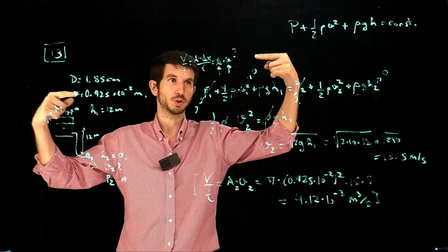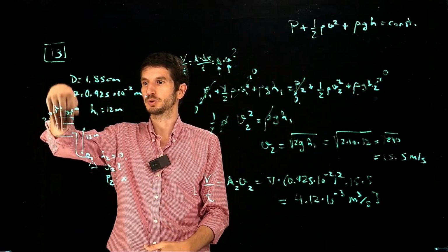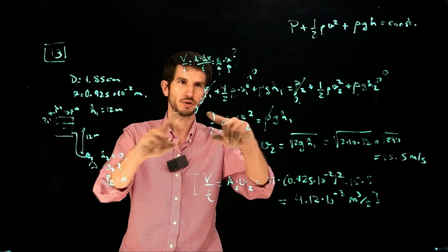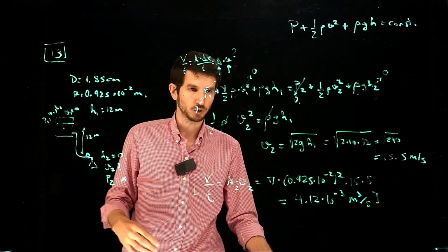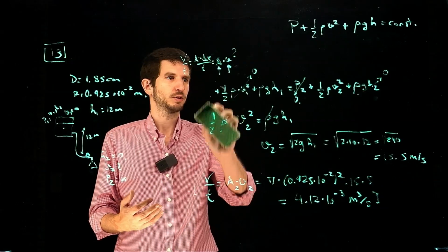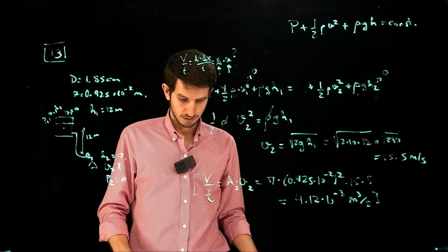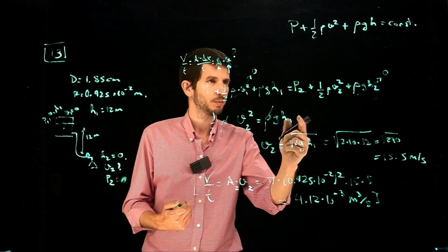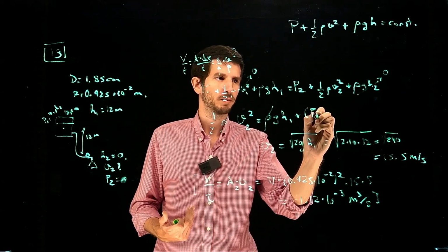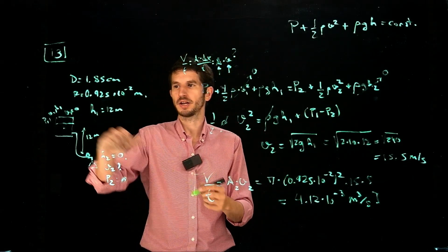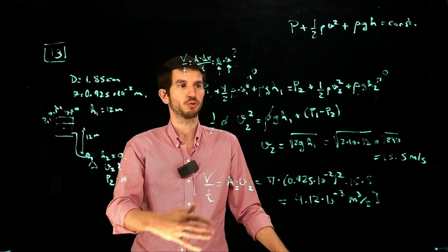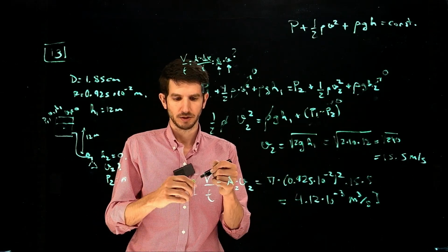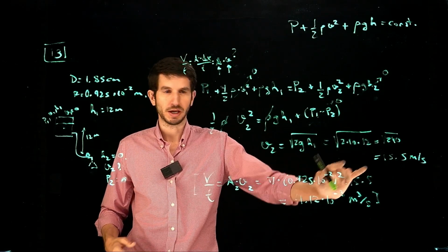Remember that pipe that we made, the pressure in here is just atmospheric pressure, the pressure in here is just atmospheric pressure. So you can take that to be 0 or just cancel it with each other. Because you could have taken this to be non-zero, right? And then we could have done that. If that is confusing, let's say P1. Then over here, we would have plus P1 minus P2. But the question is, is there any net force? No, this is just open the faucet, so it's just letting it go through gravity, so there's no extra work done in here. So these ones are going to be the same, so this is going to be cancelled, right? That's another way of saying that. So then eventually we have the same result.